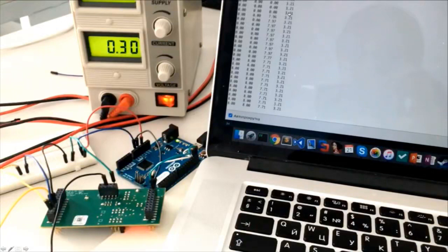So if we go now, at this point, as you can see, the 3rd channel is the one connected to the power supply. Okay, what we did was actually reverse the polarity, right? So we can generate a negative signal even though the power supply generates a positive signal, but we reverse the order. So we're generating a negative signal. And here we're starting to increase a bit. So these are like 30 millivolts. And we see that since this is supposed to only output positive values, it gets subtracted, right? So this is okay. The other two channels are fine.